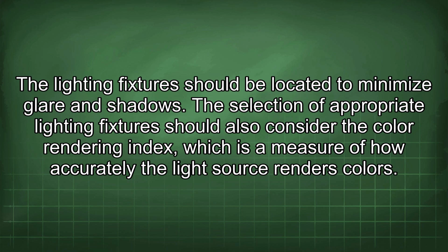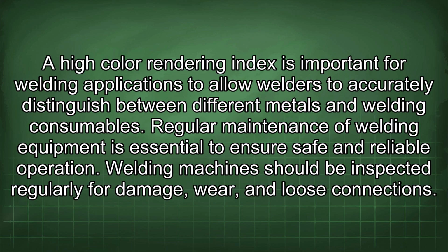The selection of appropriate lighting fixtures should also consider the color rendering index, which is a measure of how accurately the light source renders colors. A high color rendering index is important for welding applications to allow welders to accurately distinguish between different metals and welding consumables.